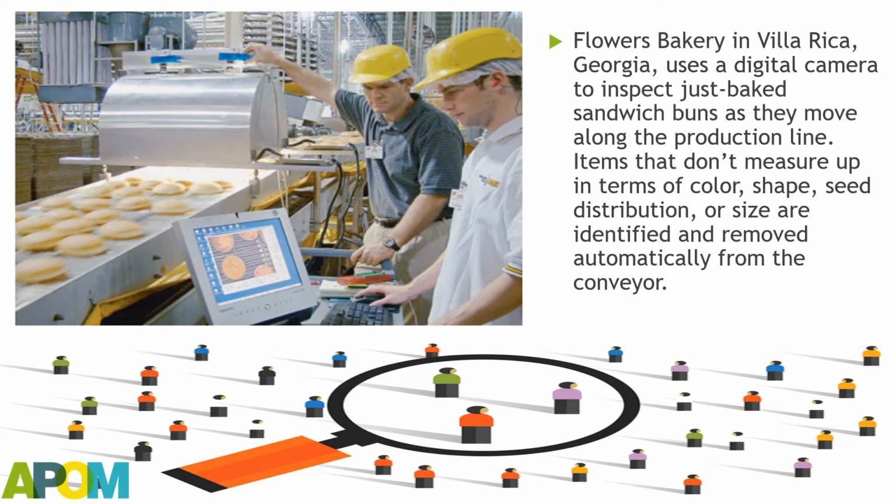A lot rejected based on an unacceptable level of defects found in the sample can be returned to suppliers or be 100% inspected to cut out all defects, with the cost of this screening usually billed to the supplier. However, acceptance sampling is not a substitute for adequate process controls. In fact, the current approach is to build statistical quality controls at suppliers so that acceptance sampling can be eliminated.